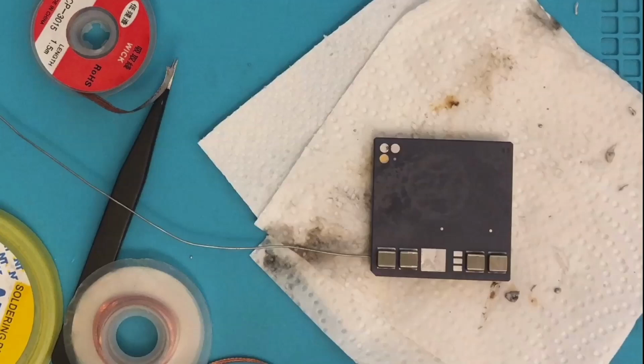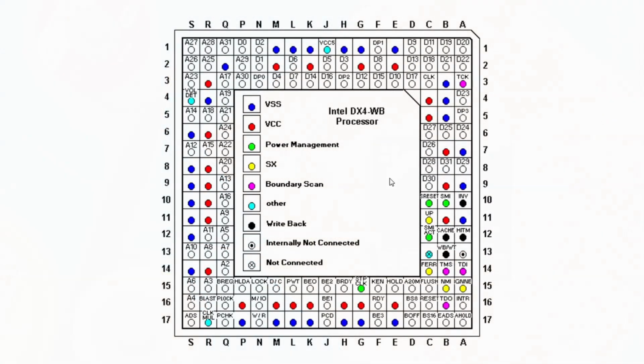Well, not really. You see, there are two types of voltage inputs to a 486 CPU. The Pentium Overdrive is very similar. The red ones are all for the voltage of the core. This VCC5 is the 5 volt input that is always there for the I/O. Now 5V CPUs like this Pentium Overdrive actually short everything together, so both the red and this VCC5, while the 3.3V CPUs differentiate these two.